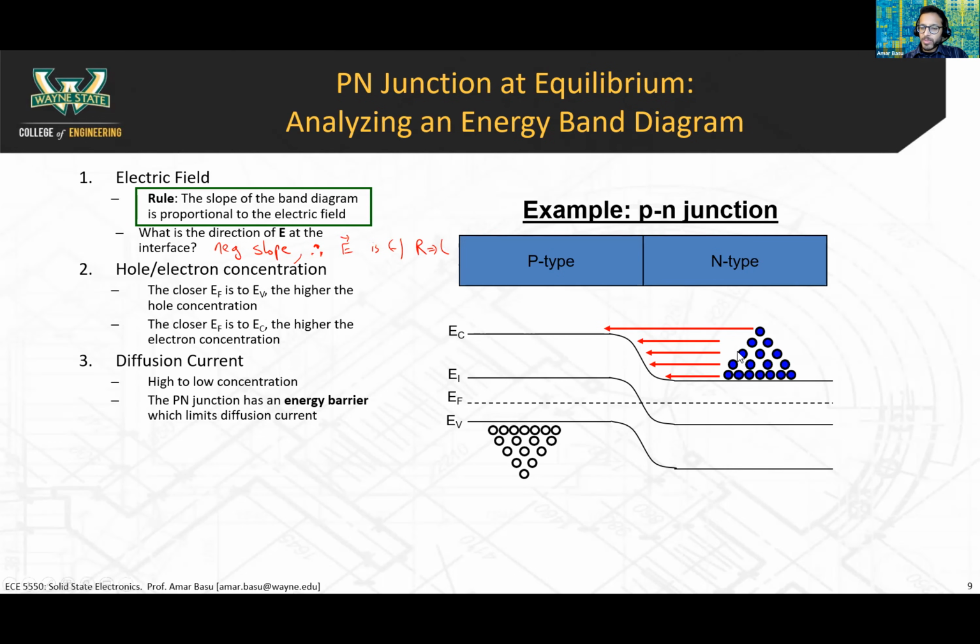Okay, so that's the first part of this diagram. That's why you see electrons moving in the horizontal direction. They can't move up. These electrons down here can't move up into the p side. So many of these electrons on the n side are not able to diffuse over to the p side. Only the highest energy ones can diffuse over. So this illustrates what's happening with diffusion.